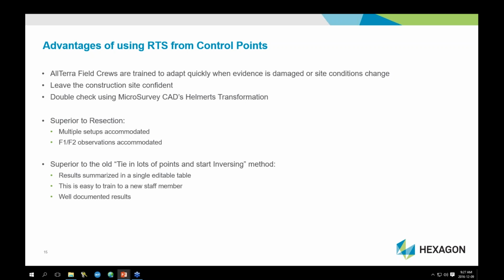Absolutely, and it doesn't take very long. When these young fellows give us a call when they're starting out with this, their call is like, okay, I've got 4 points, and my localization is giving me 3 or 4 centimeters. Is that suitable for this job? And it's like, yeah, tell me which ones you've got. I can look at it in my CAD view on the desktop. Yeah, those are fine. Maybe discard this one that's 2 lots over and see how that goes. They do it right on the phone and say, oh, great, I'm 2 centimeters and everything.